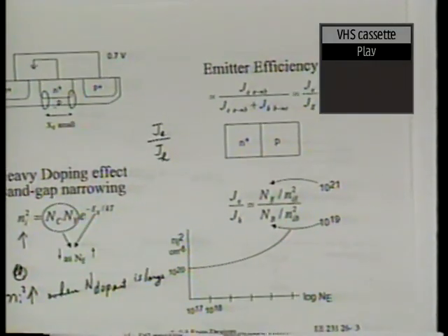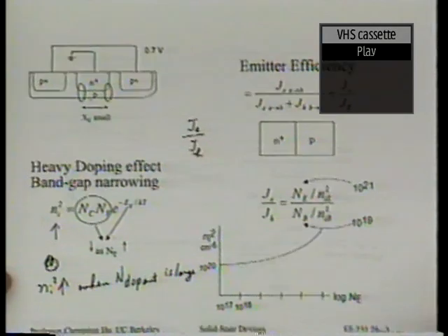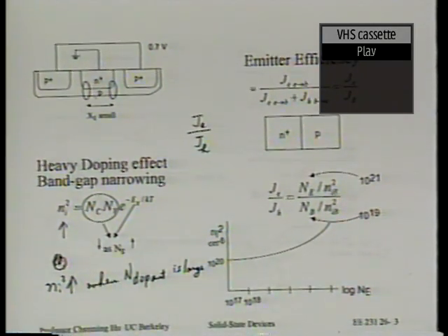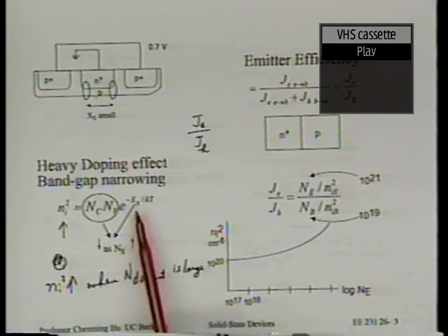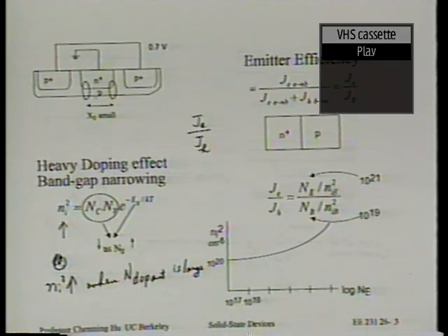It's this: don't use silicon in the emitter and in the base. For example, we do use silicon in the emitter and accept the fact that the band gap is going to be a little smaller because of heavy doping, right? We choose another material for the base whose band gap is even smaller. Hence, silicon germanium. Is that right?